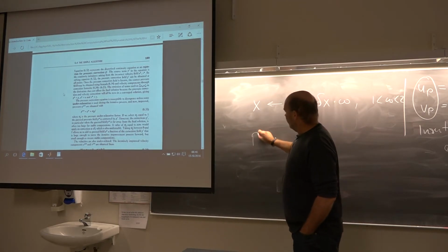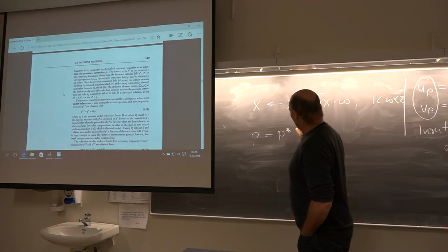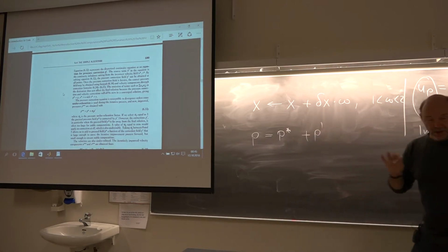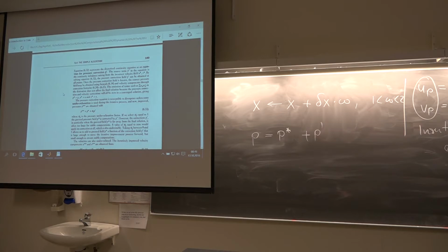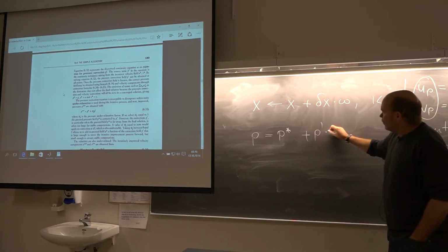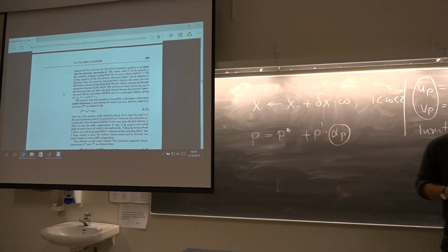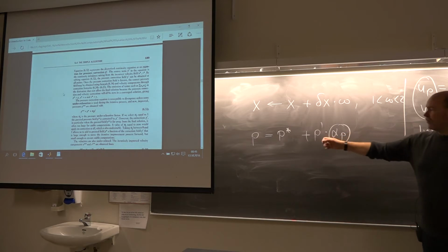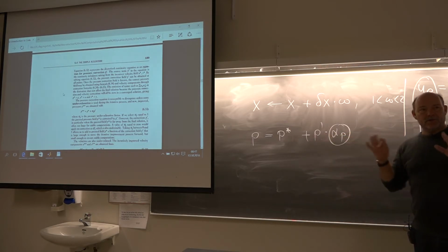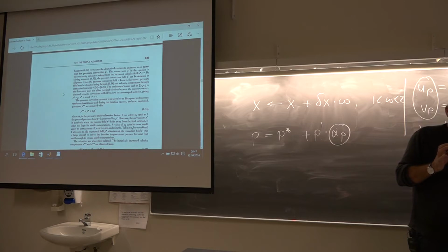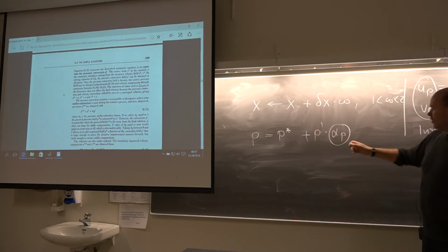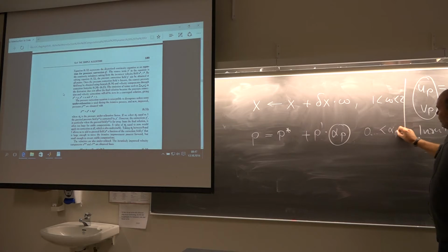So for the pressure, P equals P star plus this correction that we have just calculated from the continuity equation. Then we multiply it with an alpha for the pressure. And this alpha can be a very small number. So we find the adjustment, but we don't dare to take the entire correction. We just take 10% of it. So alpha here will be a number between 0 point something and 1, and typically it will be smaller than 1.